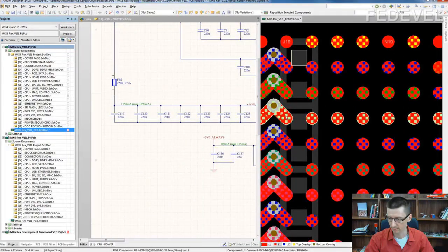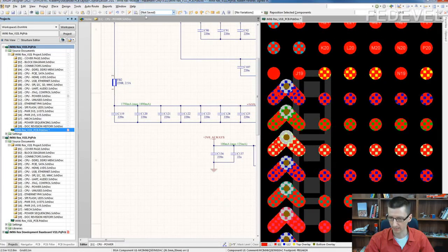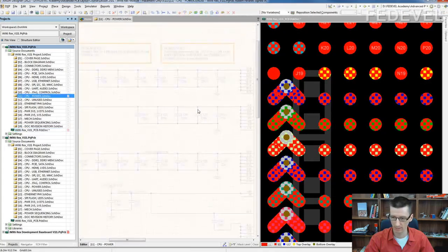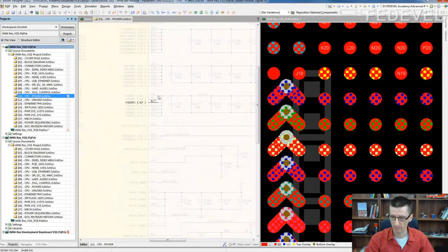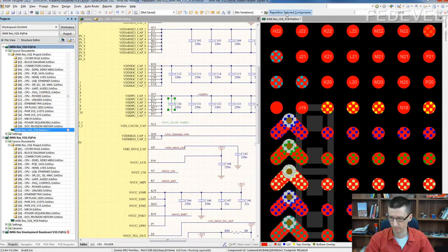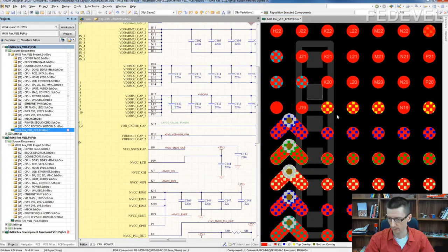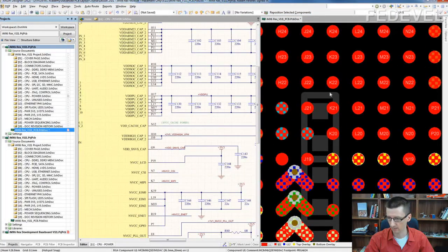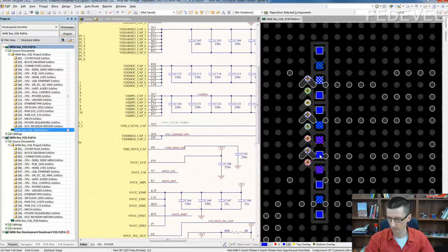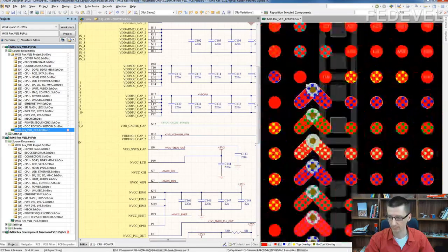See, this capacitor needs to be connected to these pins. And we need to place another decoupling capacitors to these pins. And it's going to be too far from the pin. It's too far. We still need to place something here then later. I'll show you on the bottom side so you can see it. Or I do it this way, you can see it even better.